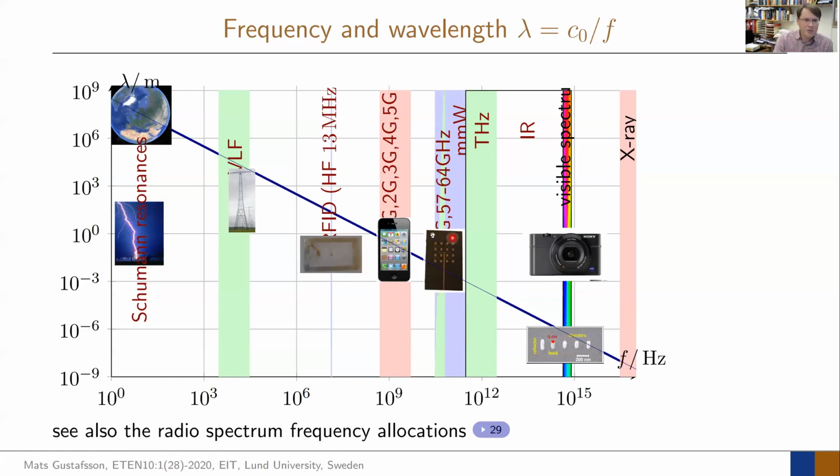So at these frequencies, you can actually fit, like you can see here, these 16 antenna elements of a size which is approximately 1 square centimeter. And then you can build an array, and we will see in the course arrays have a lot of freedom because you can steer the beam, you can make it intelligent. You cannot do that at 1 gigahertz if you would like to have it carried by a human because the wavelength is too long.